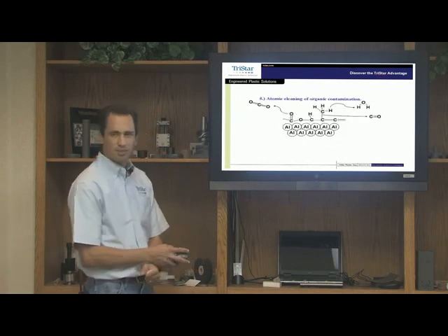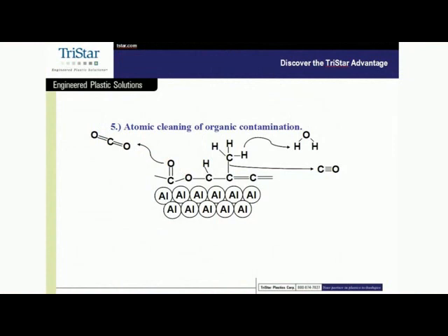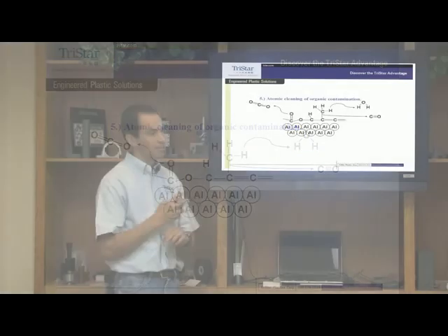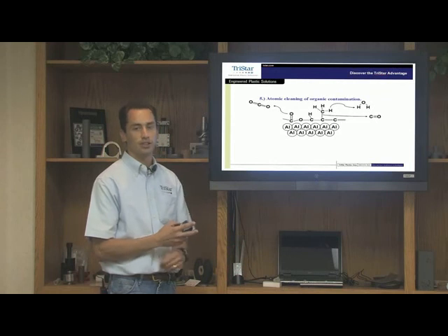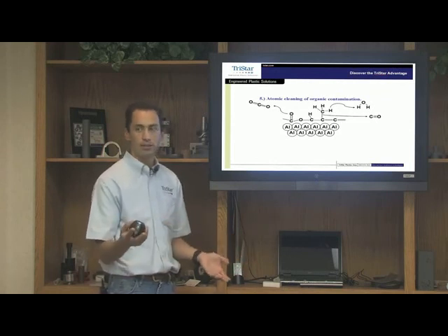Now, atomic cleaning is kind of a side note in that oftentimes we get metal substrates. In fact, we're getting more metal now than we have in a while. And that metal has organic contamination, which interrupts rubber overmolding operations. So we receive this metal, and we're able to clean off the organic contaminants, fingerprints and oil, and then deposit a functional intermediate between the metal and the rubber overmolding. So it's not an adhesive like some of the other metal primers out there. We actually have an inorganic treatment that is the intermediate between metal and rubber material.